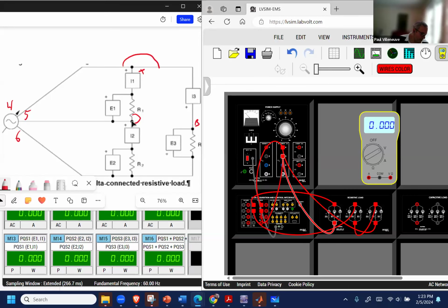So this is where it gets a little squirrely because you can say, hey, wait a minute, Paul, how is this working? Well, I'm at the bottom of R1 and I'm measuring the current. I'm connecting the bottom over here, but I'm also doing this one, which goes directly into here. So essentially what I'm doing is I'm forcing it just to measure the current through R2.